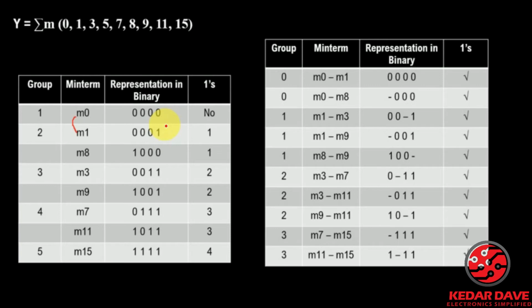So what we will do is put only a negative sign, a dash, on that particular section. On that section we are basically making the change, this min term is getting changed, and we put only a dash over there. So here it will be a dash, or we can say an underscore, not zero. There is a mistake in this particular area, so mind one thing, it will be a dash over here, this way.